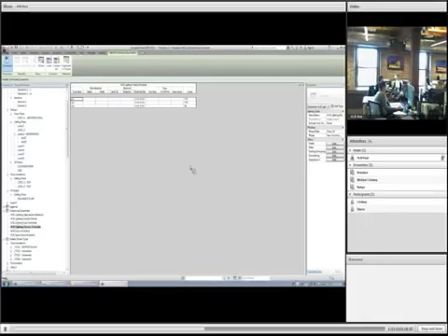Awesome. So, because it is so easy to copy from level to level, if you run into a mistake like that, I would recommend deleting the offending levels or the areas where you don't have it right. Make sure you get the one floor plate correct again. Oh, you would just completely delete. I would completely do it, and actually go back to a 3D view.